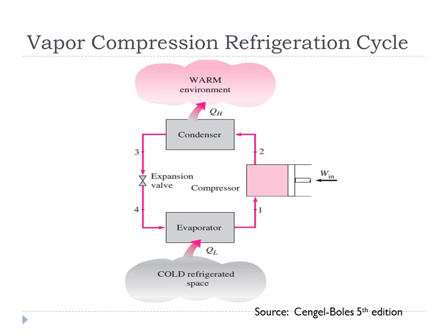At state 2, the refrigerant would enter into condenser. At the condenser inlet, the pressure and temperature of the refrigerant are very high, because the work energy which was consumed to compress the refrigerant vapor was converted into internal energy, and it raised its pressure and temperature both to a very high level.